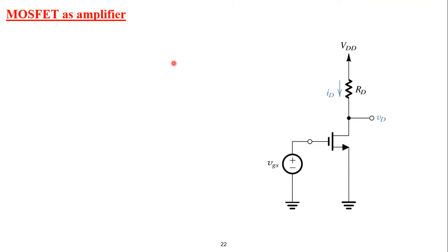Now, in this part, we are going to demonstrate the AC analysis of MOSFET. If you remember, in the first part I mentioned that there is no AC analysis without a DC analysis. Why do we need a DC analysis in an AC circuit? This is simply because a MOSFET circuit cannot operate with only an AC source. This is very simple, and you can easily recognize it.